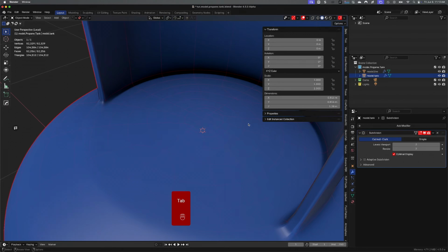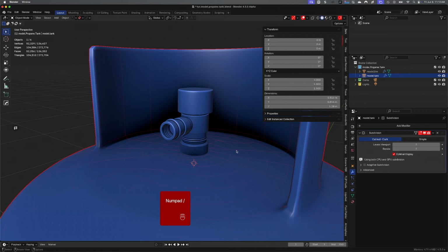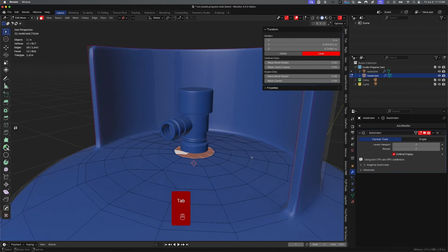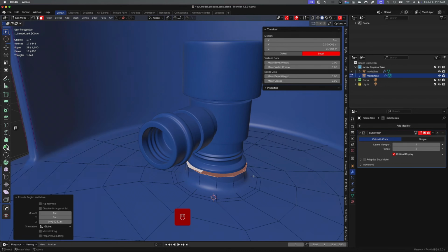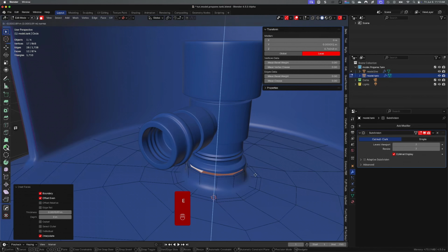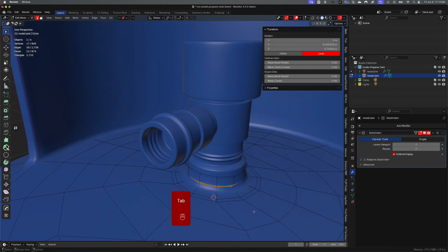So one thing I did not show you guys is how I pulled up that little back piece. Basically what I did was I created a bevel. I scaled a bevel out, which basically made two edges right there, two separate edges in a ring. I selected the ones I wanted and I literally extruded them up. That's all I did. And then I did edge creasing, edge mean crease on the sides of it. You can see in red here in the back of the screen where everything needs to tighten up a little bit. So it's non-destructive. It was super easy.